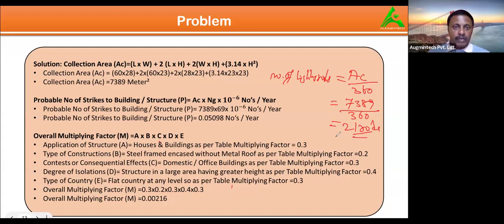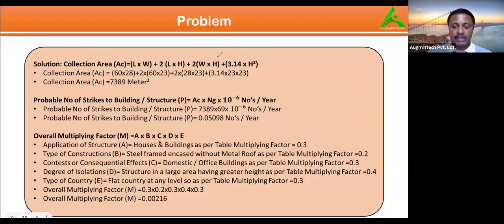That's what it is. And if your collection area is smaller, yes, a minimum number of rods. And all these rods you can install usually at the corner of the building. Okay, maybe I'll include this, or else I have a separate lightning calculation for another example. And all these things you'll be receiving, from my calculation, from my projects that I'll send you.